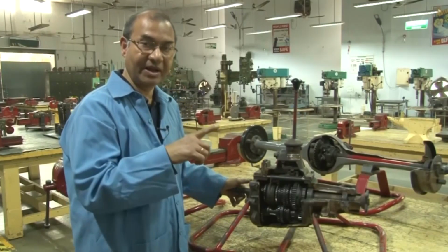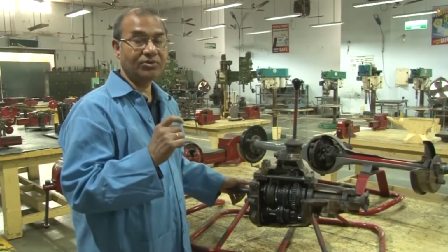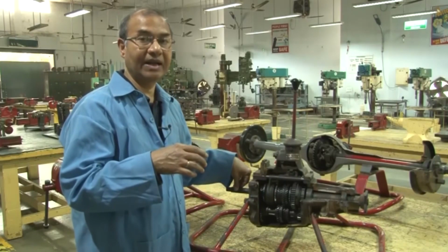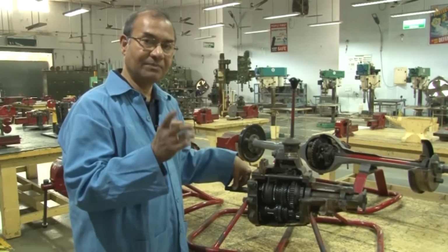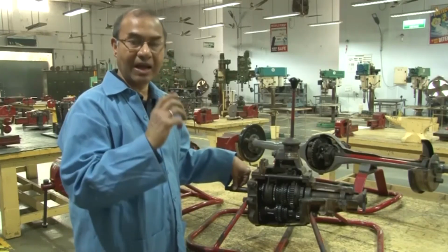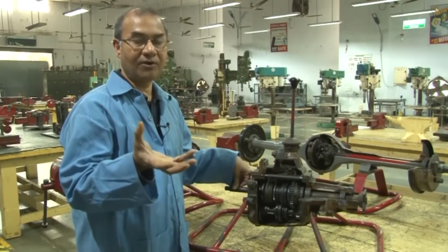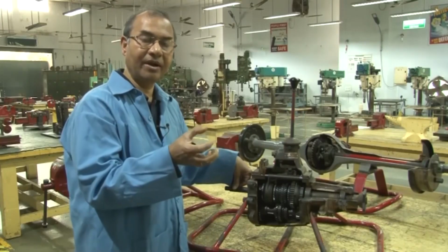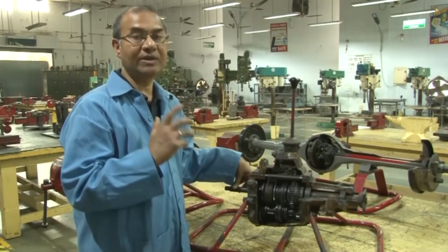So, this is N1 by N2, which is actually less. Now, another thing is that in the first and second gear you have to have a larger torque. As the RPM is less, the torque will be higher, and as the gears are changed, meaning you are transmitting from a bigger gear to a smaller gear, the RPM will be more and the torque transmitted will be less.